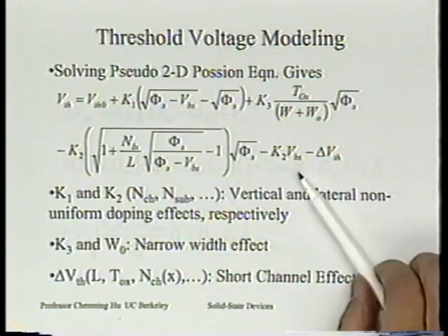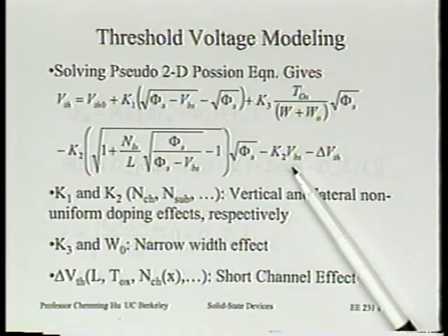So take a look at this equation here. What do you see there? Linear. And it's also a body effect. Now, does this ring a bell to you? Why should VT be a linear function of body bias? Okay, that's good. And so that will be appropriate for a device with retrograde technology.